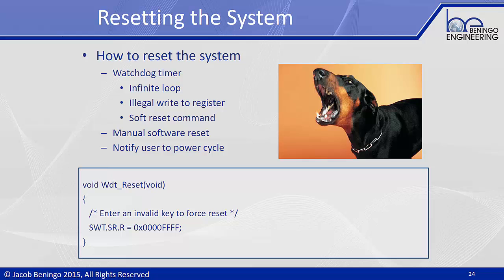The first is that we need to enable our watchdog timer inside our application code and inside the bootloader. We need to make sure that we integrate the watchdog timer petting routines, which make the watchdog happy and not reset our system. We need to make sure that they're tightly integrated into the bootloader and/or the application code so that it isn't a useless watchdog timer. Basically, we're going to enable the watchdog, and one of our options, when we want to reset the system, is to just go into an infinite loop. Don't pet the watchdog anymore and just wait for it to time out, get angry, and reset the system.